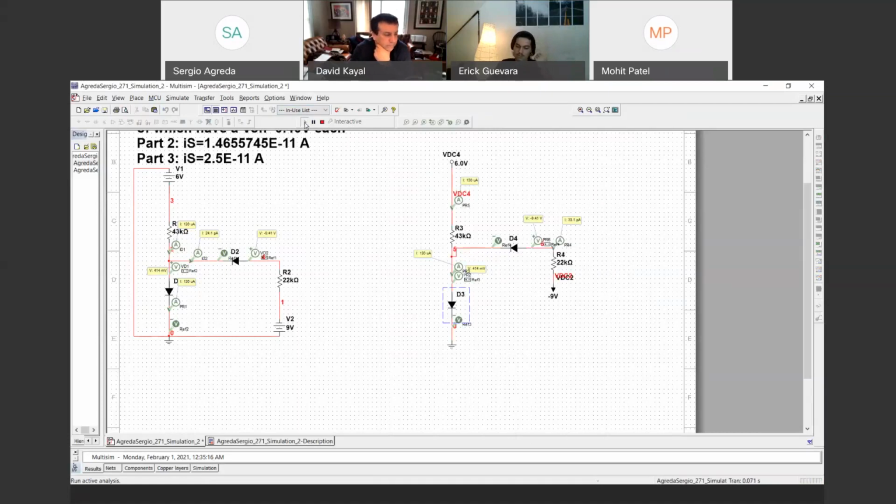See what's the behavior. Cool. This is nearly exactly what we calculated. We got the correct current, but not the same voltage drop that we chose for this diode to have, and the same for the voltage across this diode when it's off. Now that's odd, because it should be accurate. This is part of what makes a diode a nonlinear component. It is not at the exact values, so you have to play about with the factors that you have.